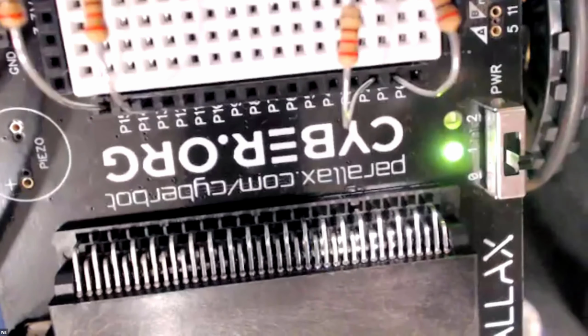I think I see it. Oh, what is it, Alan? Okay, if you move your robot so that we can see all of your pins closest to cyber.org, so you can see the numbers. Now, there you go. So you're in pin 15 and 14. You should be in 14 and 13, so you'll have to change your code. Oh, okay, let me give that a shot. So move each one down. That way your 2K and your 220s are in the right spot.